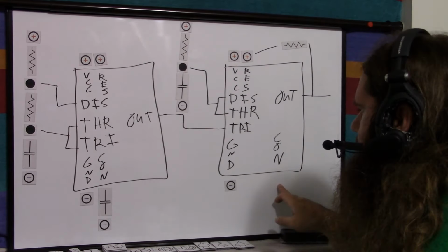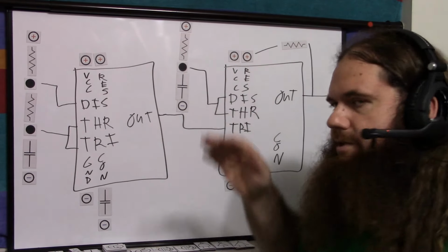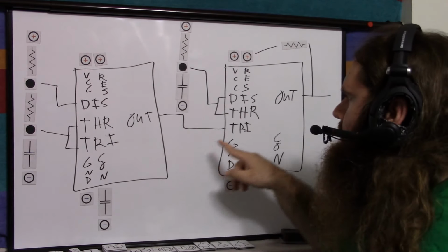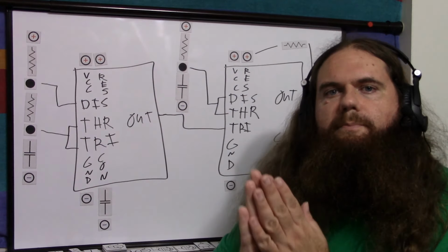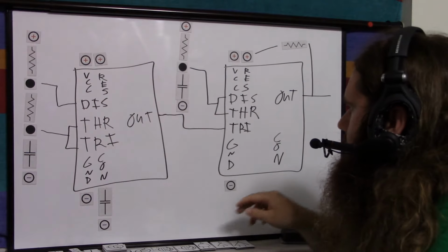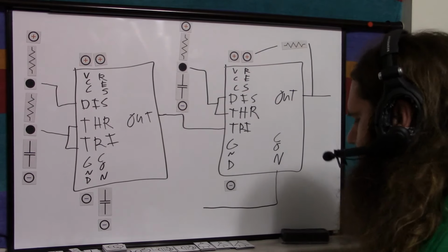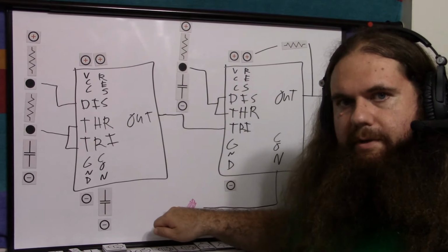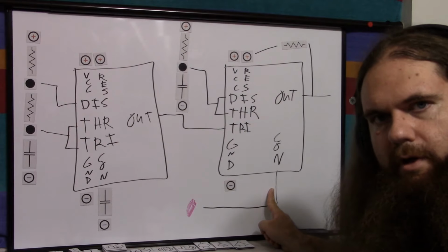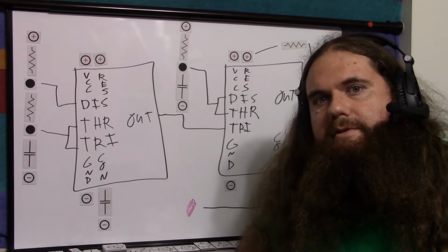That's how this works. If we increase the control voltage, then it's going to take longer for the RC network to charge and raise the threshold voltage high enough to actually turn off the timer, so the pulse is going to be longer. So that's all it is. Control is another input. You just apply a voltage, and I'll just put that to say that's an input. This is how we set our PWM. You apply a voltage to control on the monostable to change the duty cycle, and then this sets the period.